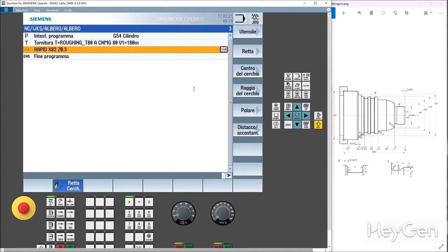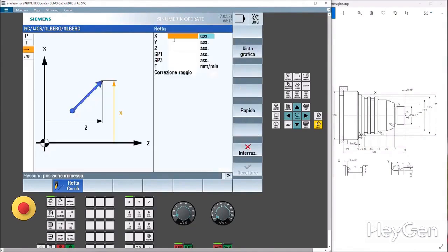So we set it to rapid, accept that, and now the machine moves close to the workpiece, so straight to X. I'm going to face it, so -1.6. Why 1.6? Because the insert radius is 0.8, as I already explained in the previous videos related to tool radius corrections. If I chamfer at X0, there will be a bevel left from the tool's radius that won't be removed all the way to the center of the piece.